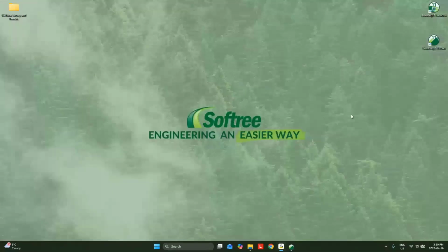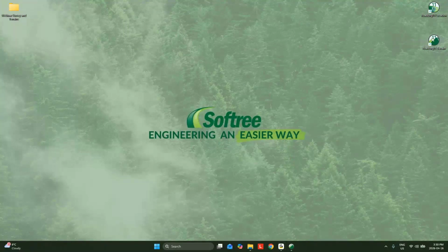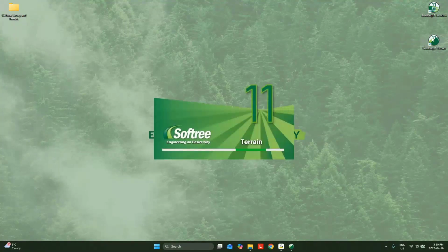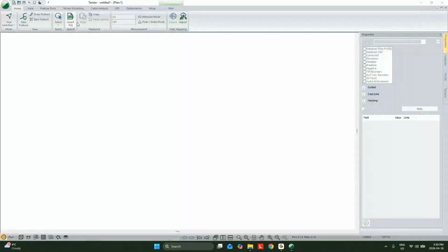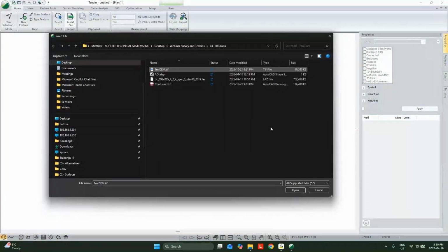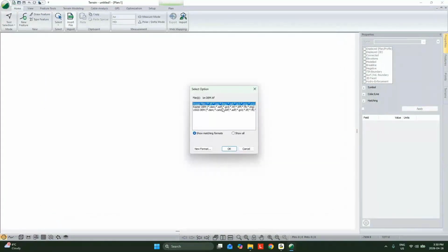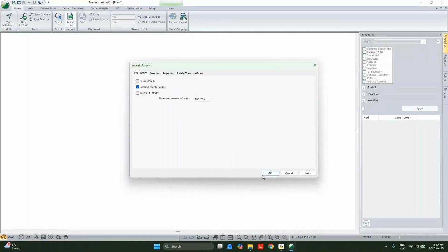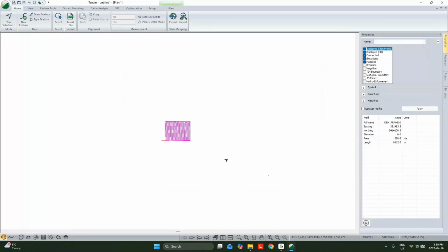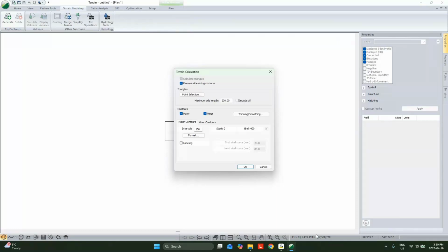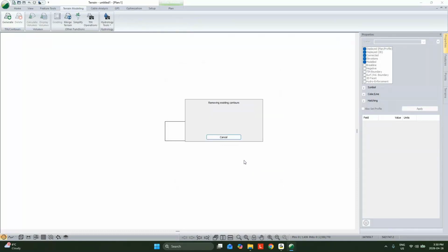Now let's back up here. And again, we won't use the actual thinning tools. We'll just look at some of the differences in format before we use the thinning tools. We're going to click Insert File. We're going to select that DEM this time. So this is a TIFF. Now the TIFF could be an image or it could be the raster data. So we're going to select that it's raster data. We'll bring this guy in. Loads much faster. We're down around 2.5 million points.